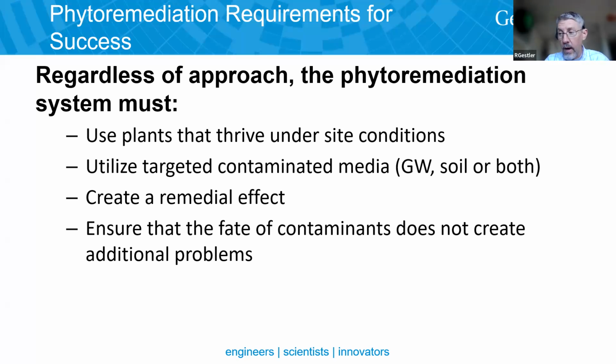So you have to pick the right plant species for the right site to understand the climatic conditions, the role that contamination may play, etc. Your phytoremediation system must utilize the targeted contaminated media. In other words, if it's a groundwater site, they must root down and start to exert some influence on that impacted groundwater, or they're simply not going to have any benefit.